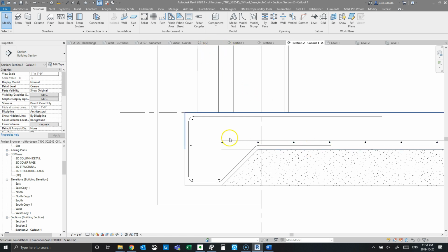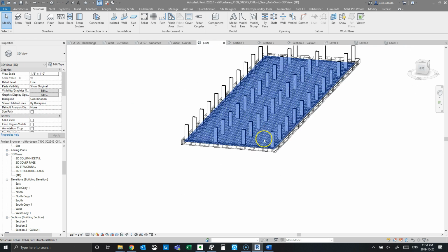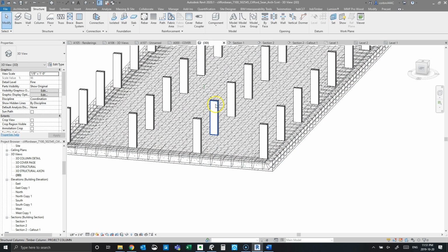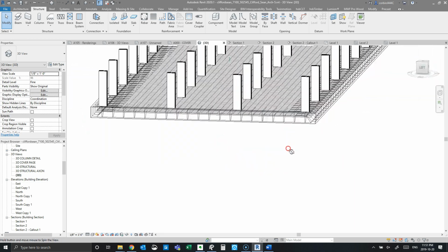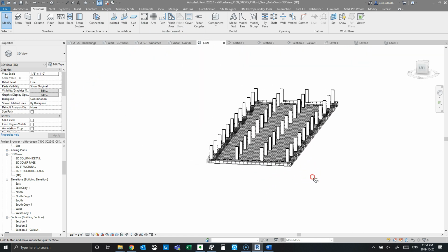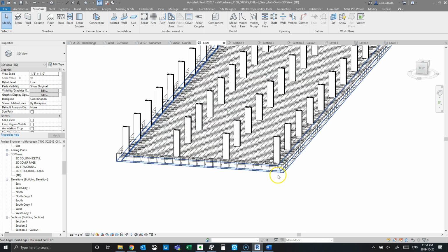Floating slab wouldn't necessarily be sufficient for a building like this, or at least the edges would have to be thicker, and then I guess in the middle where you have these columns you'd want to do a pad footing there. I'm going to do another video showing how to do a frost wall style foundation with caissons, and in that video we'll go over how to do the footings for that type of foundation.